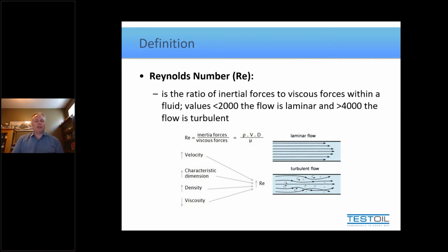You want the ability to really try and pick up the particles, suspend them in the fluid, and bring them towards some other end of the system, right? Towards a filter, towards a reservoir, to be able to get them out of the critical areas of the lubrication loop. So when we do laminar flow, this doesn't generally pick up much. It barely pushes them. So you're not likely to get a whole lot of movement on any particles that are contained within the piping or the coolers or the reservoirs or whatever else is connected to the lubrication system.